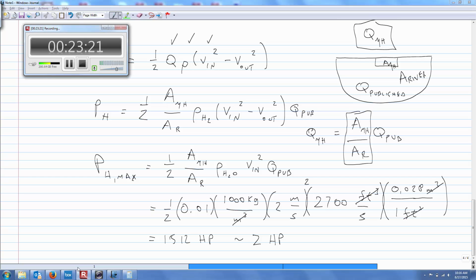But you can get some baseline numbers right now with a drill that runs 1,250 RPMs at top speed, and I get this many volts. So that gives me a starting point. I can tell you right now, the drill will only spin it to about 9.1 volts. What do you need to charge a 12-volt battery? At least 12 volts, right? Drop out voltage. So you're going to have to add some numbers to that, so obviously, you're going to have to spin it faster. 13. So now's your time to play with that.